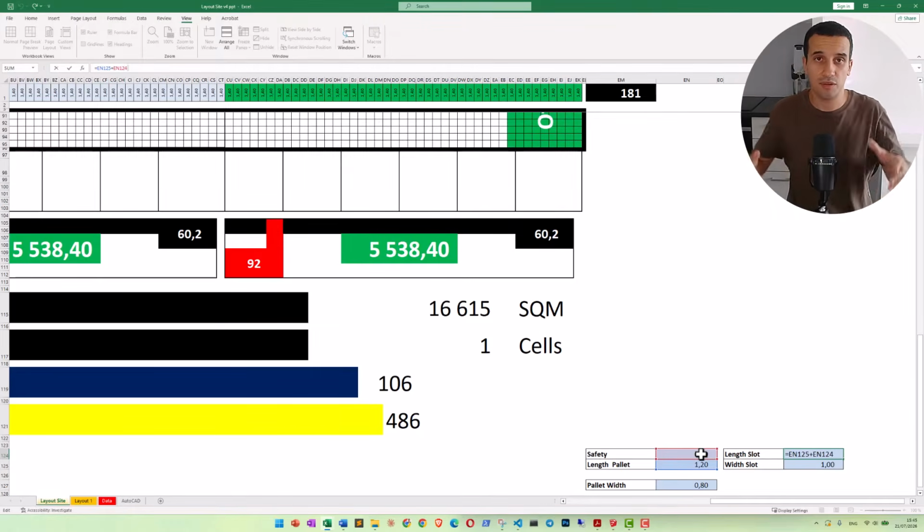So imagine that you have the racks that I showed you in the 3D layout. So you have the length, the width, and you want to know how much square meter you take. So you take the dimension of the pallets and then you put a bit of buffer because the rack will take a bit more than what the pallets have. Here, the safety buffer was 20 centimeters. For the width, so here we are talking about 120, 80 pallets.